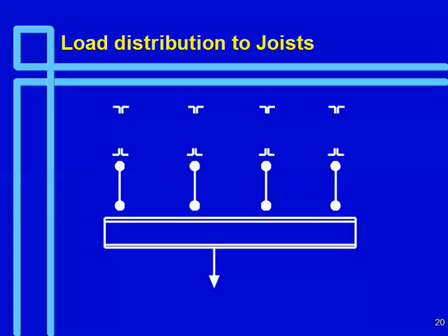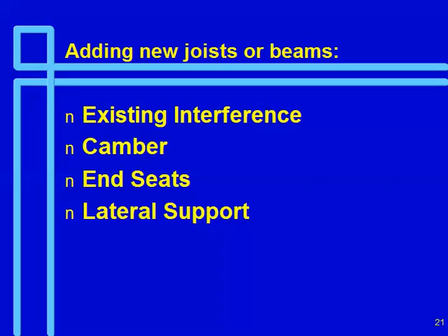I can design a beam, and I can actually design like a truss interior here to spread it too if I don't have the headroom. Okay? And it goes back to simple beams on elastic foundations theory as to how to do that. Or you can just put it in a computer model. Okay? So I urge you to think of that first as a way of handling the reinforcement, or not having to reinforce.